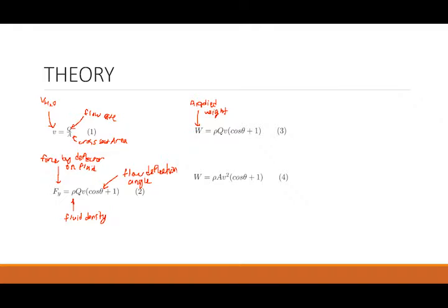When we apply the energy equation between the nozzle exit point and the surface of the deflector, it shows that the magnitude of the flow velocity does not change as the water flows around the deflector. Only the direction of the flow changes.